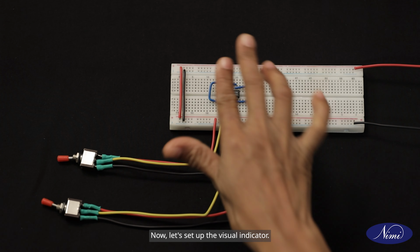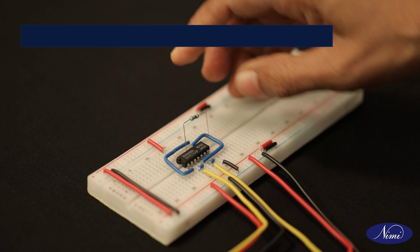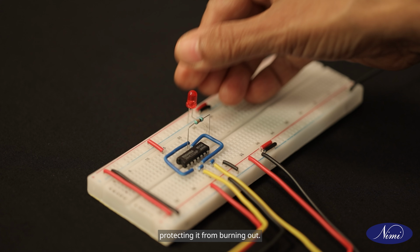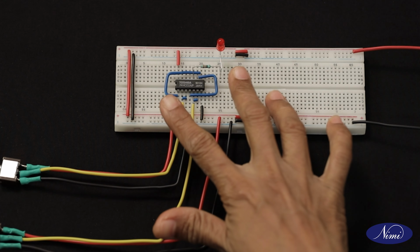Now let's set up the visual indicator. Connect a resistor to the output pin number 10 of the IC. This will limit the current to the LED, protecting it from burning out. Then attach the anode of the LED to the free end of the resistor and cathode to the ground. This will help us to see the result of our AND gate's output clearly.